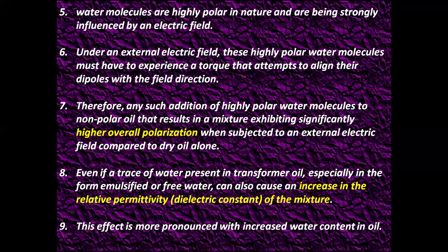Number 8, even a trace of water present in transformer oil, especially in the form of emulsified or free water, can also cause an increase in the relative permittivity, that is dielectric constant of the mixture. This effect is more pronounced with increased water content in oil.